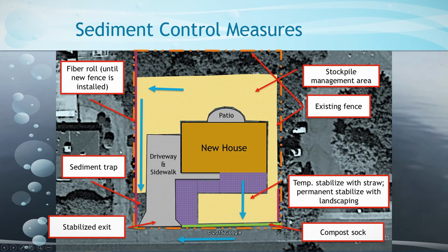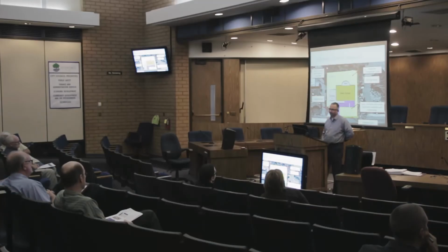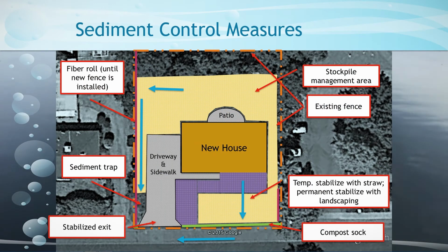Overlaying it with some of our erosion controls, notice that right here I put our fiber roll. The reason I put it here was we didn't have much of a fence there, and flow was generally heading that direction, so we put a fiber roll there just as good perimeter protection for sediment control. Although the way we graded it, water should flow south from there rather than continuing west, and it should come along the side yard towards the front.